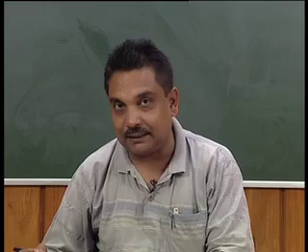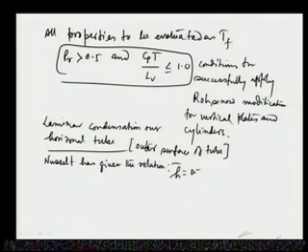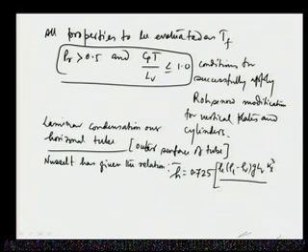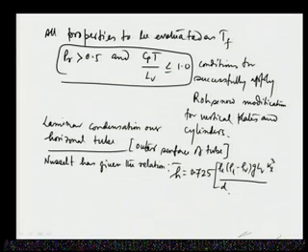It is similar to what was derived, and in this case the average heat transfer coefficient h bar is given with a relatively different coefficient, 0.725, and then we have rho_L into (rho_L minus rho_V), this part is known, then g is the gravity, L_V is the latent heat of evaporation, and then k_L cubed. And then we have D in place of L; D is the diameter of the tube, whereas in the case of a vertical plate it was L. Then mu_L, and then (T infinity minus T_W), and the whole to the power 1 by 4.